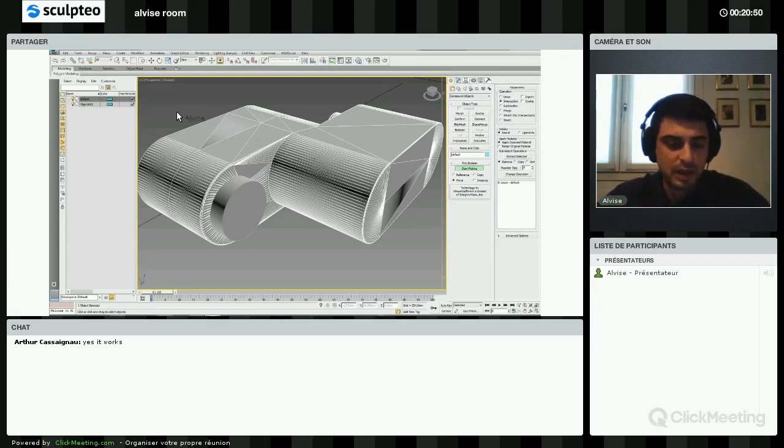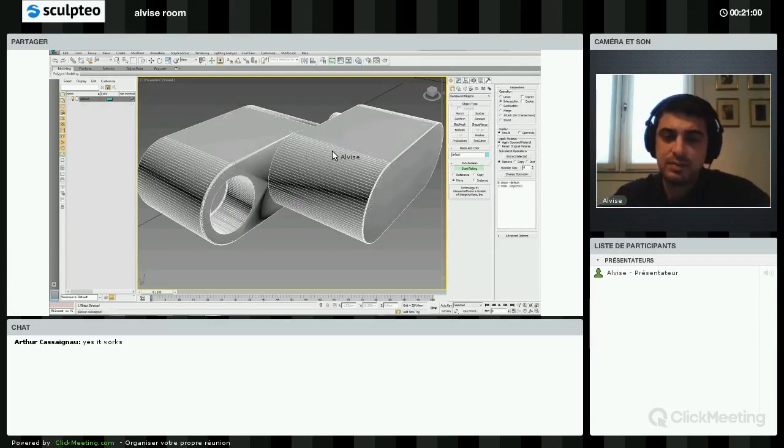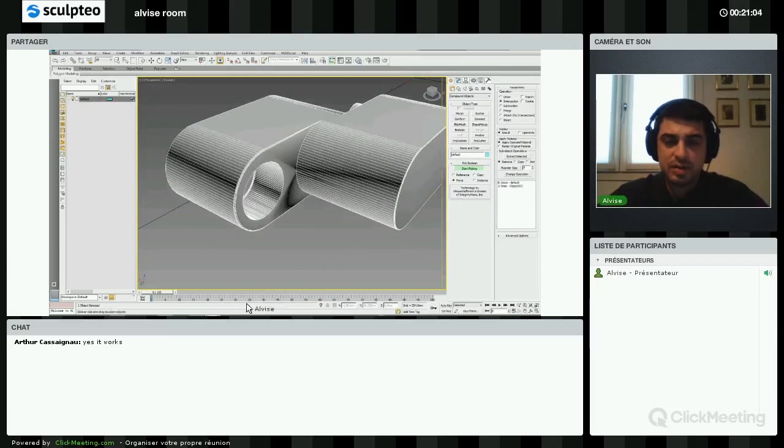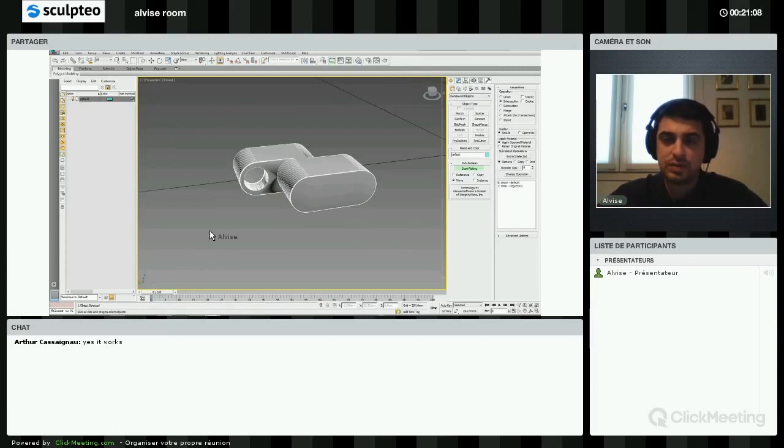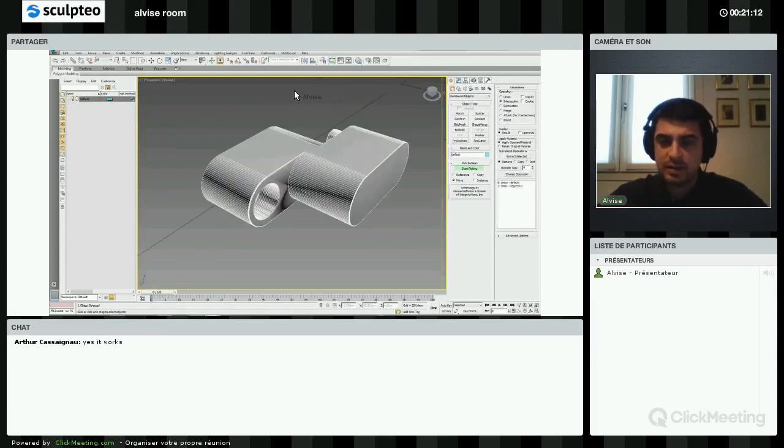Okay, so now I modify this half part properly, move the face and make the cylinder bigger so that the clearance is reached. The last couple of things to do is mirror it with the symmetry modifier. Slice along the mirror, select it.